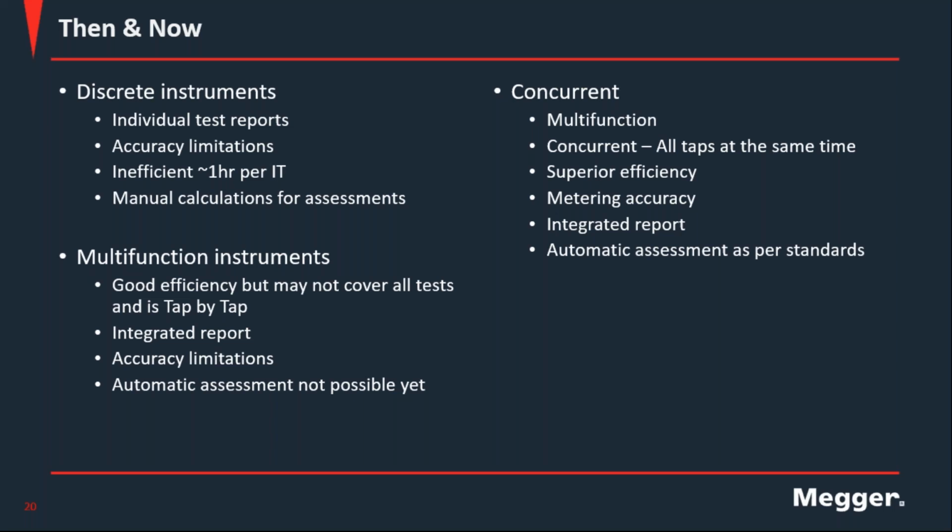And you can test not with one single instrument, you can test different types of instrument transformers. So there's not an instrument for VTs, there's not an instrument for CTs. You can get an instrument that can do all of them, and even capacitive voltage transformers that are also kind of an additional, or have their own complications. So you can test all the instrument transformers with one single instrument, and everything is in one single place, so it can perform the assessment.